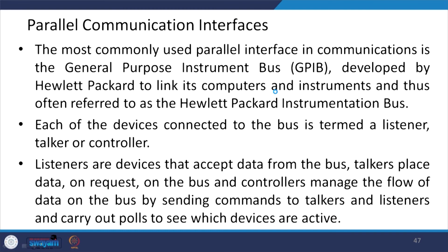Okay. The parallel communication interface, as I said, the most commonly used parallel interface in communication is the general purpose instrument bus, that is GPIB, developed by HP to link its computers and instruments and thus often referred to as the HP instrumentation bus.